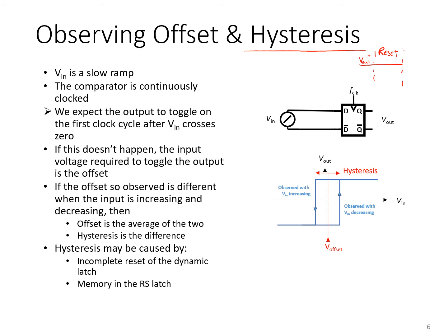Let's say it's V out plus, whereas the other half of the differential output may be down at ground, and so when it enters the reset phase, some pull-up transistors are generally activated to pull it back up to VDD. Now imagine that those pull-up transistors are not fast enough, not strong enough, not delivering current to those nodes quickly enough to fully recharge them all the way back up to VDD. And this can also arise if the time allocated for the reset phase is insufficient.